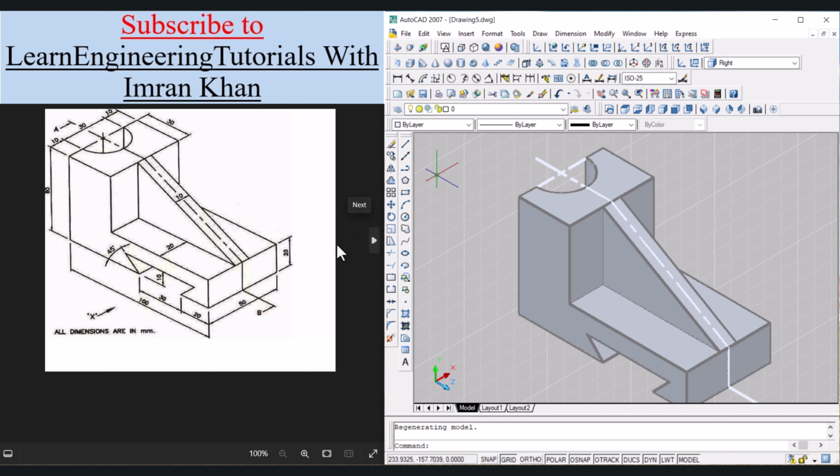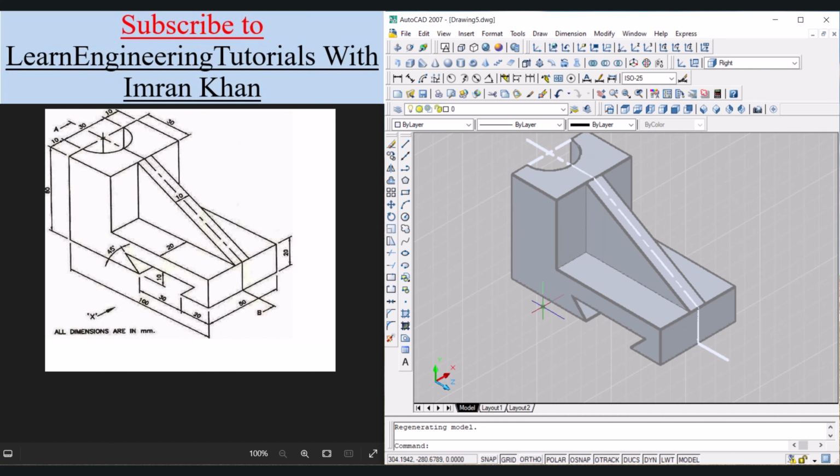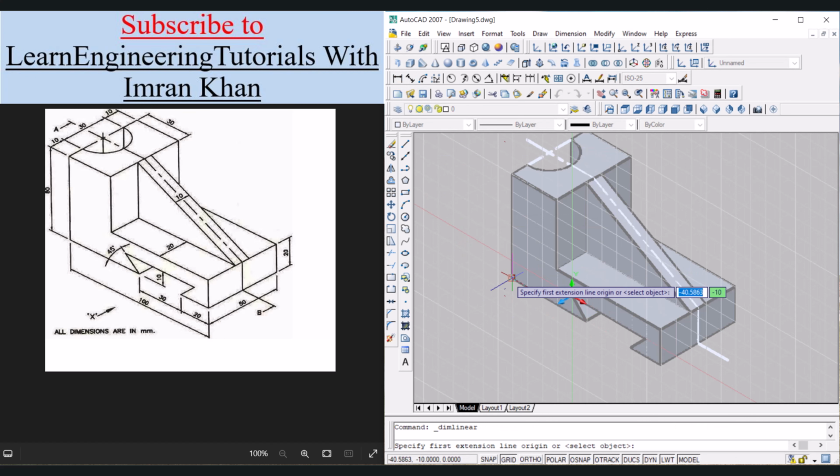Now all we have to do is to perform the dimensioning and add some leader lines as well. So for dimensions we have to use face UCS option. Click on face UCS, select this face, accept this. Now click on this linear option, click on this endpoint, move the cursor in this direction and click.